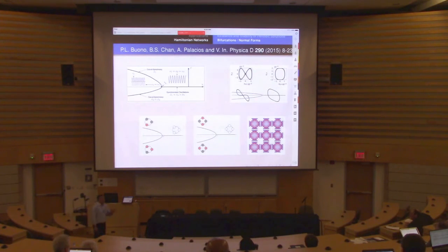So the analysis allows us to describe not just how the patterns are going to bifurcate into the synchronized regime, but it also gives the engineers that lambda star which is critical, which can be calculated for any network of any size, so that they know exactly where they need to operate the network to obtain the complete synchronization. And this is the actual MEMS realization. This is the layer of what you see in each of these units. This is a 3x3 matrix of gyroscopes. So the idea is at the top there will be a second layer that will actually do the connectivity, so we can actually create any type of coupling structure.